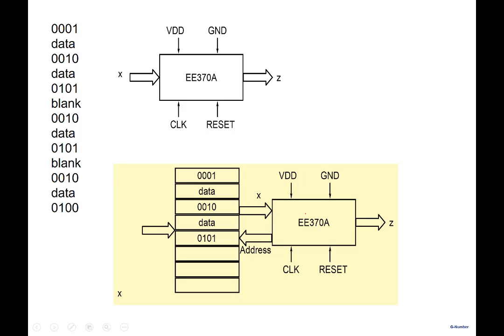And now you're seeing what it is evolving into. A set of registers will become a memory, and this one can do not just adder subtractor, but all kinds of logical operations, multiplication and so on. So it becomes a programmable digital system. So it becomes a microprocessor. The whole thing is evolving towards a microprocessor here and a memory here. So that's what a general purpose digital system is: a processor connected to a memory. That's what it evolves into.